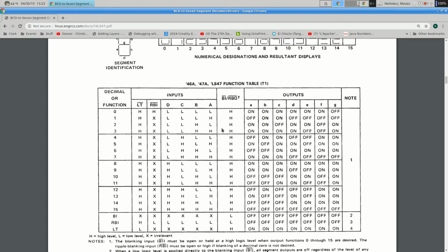And so part of working with digital circuitry and digital devices is being able to read data sheets, right? And being able to think about this in terms of its behavior instead of its circuit diagram or its ones and zeros. Logically, what is this doing? Kind of like with a multiplexer. If we look at the truth table for a multiplexer, it's just a bunch of ones and zeros. If we think logically about a multiplexer, it's a steering circuit. It chooses an input to send to the output. And that's often the more useful way to work with this.